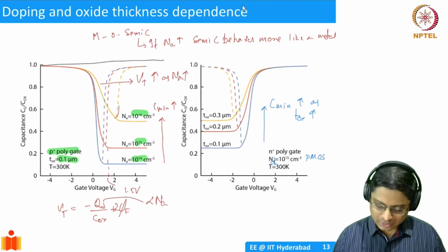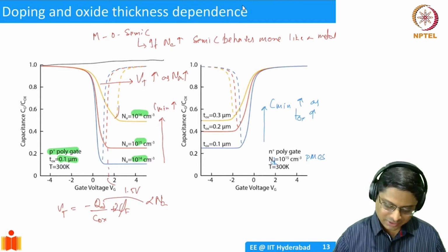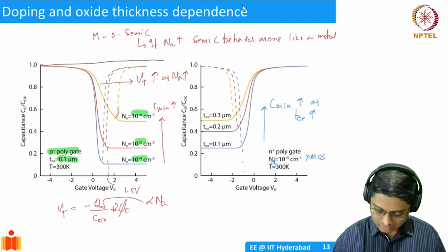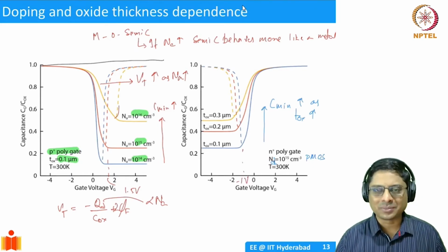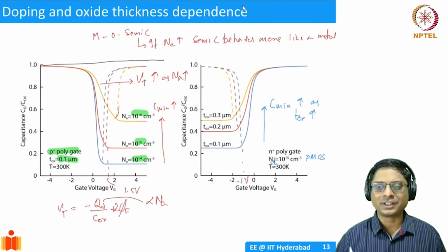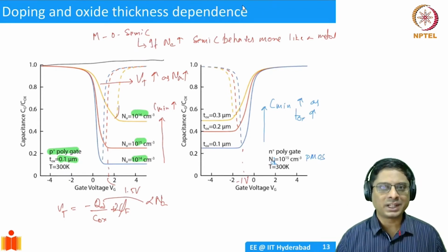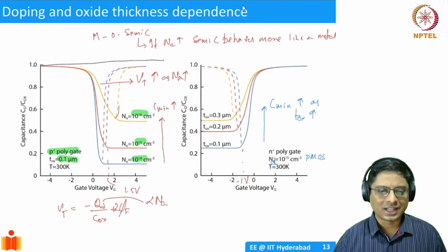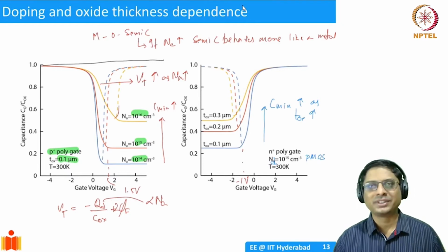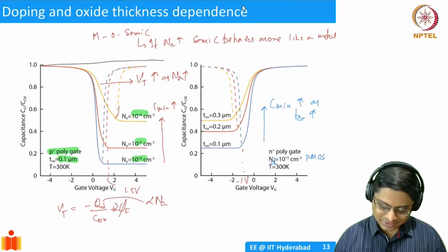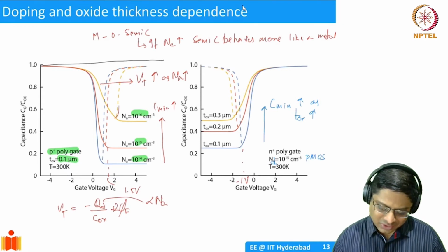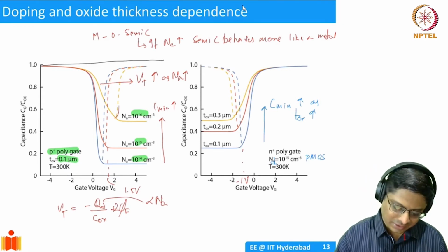Okay, so you see that Vt is typically in the range of 1 volt. I'm deliberately mentioning this so that I'll compare it. I'll ask you also to compare. In the last video, we mentioned that if you have an N-type substrate, use a P plus, and if you have a P-type substrate, use an N plus. Okay, that has advantages. It will lower the VT, I said, right? So you can verify that yourself. Okay. So anyway, as the thickness of oxide is increasing, we explained this trend already, and there is a small dependence on VT again here, right?